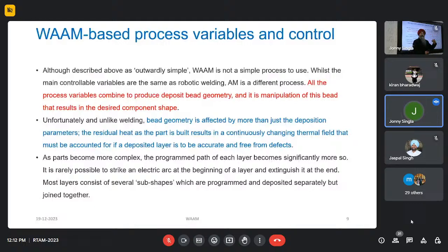Then there are things we cannot see with the naked eye. These are the radiations. So radiation is also involved. But just imagine when I plan to print a part with 100 layers, and I am at the 30th layer. When I have to go for the 31st layer, I need to control precisely what should be the temperature associated with the 30th bead prior to depositing the 31st pass. So that kind of micromanagement related to heat is required.